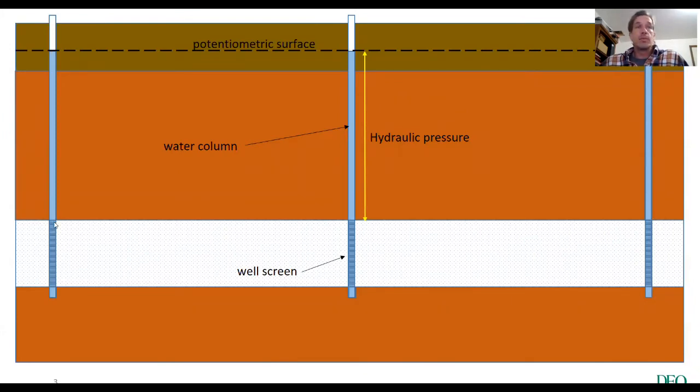This is a very important part to understand, is that they're open in the same portions of the aquifer. And the reason they're open is because there are screens in the wells. Since these are coastal plain wells, you have to advance casing all the way down through your aquifer and then screen it so that you can allow water in.